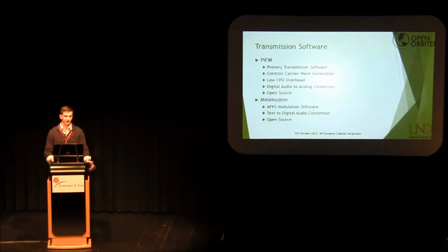Following that, we have a program called Minimodem, and what this does is it takes input data and converts it into a wave audio file that we use to transmit with PiFM. It does this by modulating the data in an audio frequency shift keying, so AFSK modulation. And again, this software is open source.